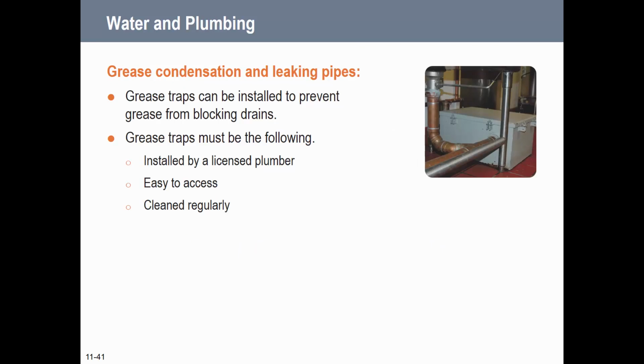So when we look at grease condensation, these grease traps are normally installed in a place that uses a lot of this to prevent grease from blocking drains. These are important. They must be installed by a plumber, cleaned regularly. This isn't a fun duty, but it's something that needs to be done to ensure that we are, it's really a safety issue too, but it can also clog up your drains, etc. So grease traps are really important.